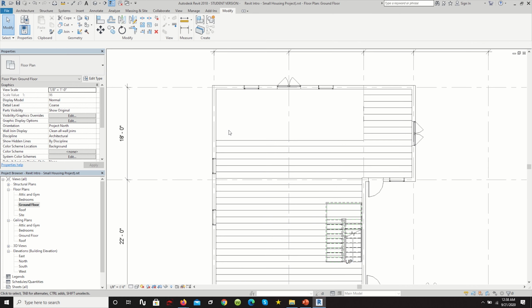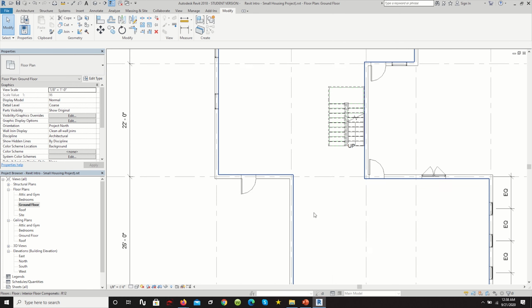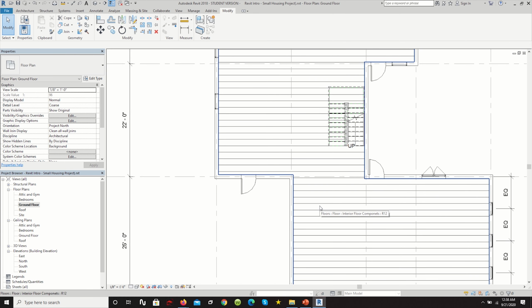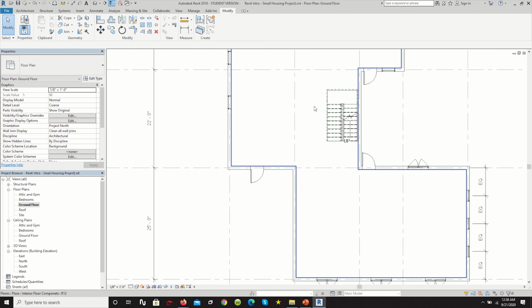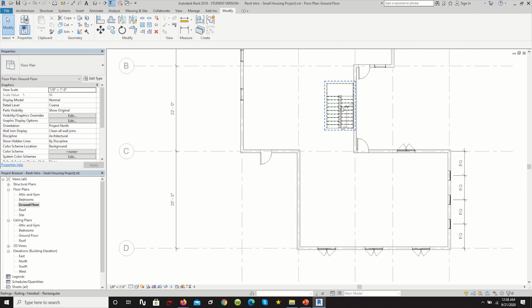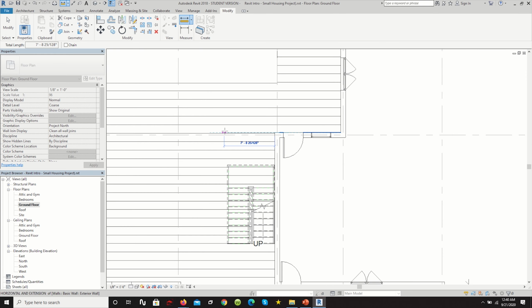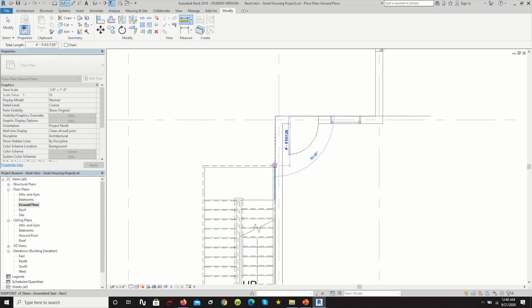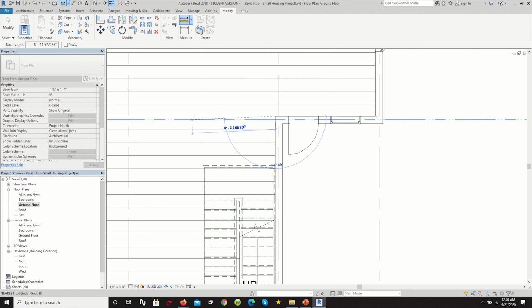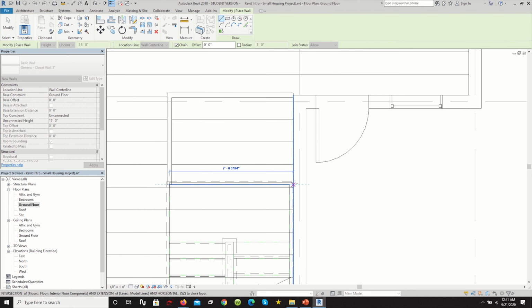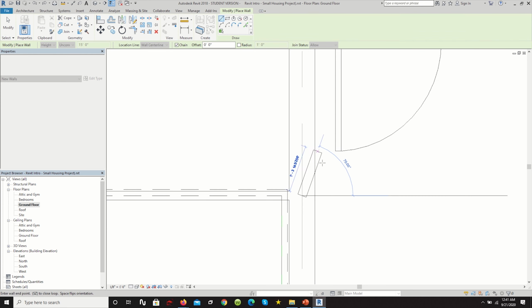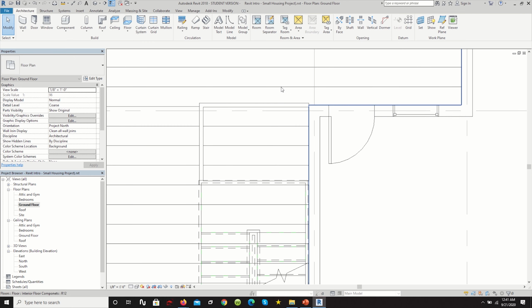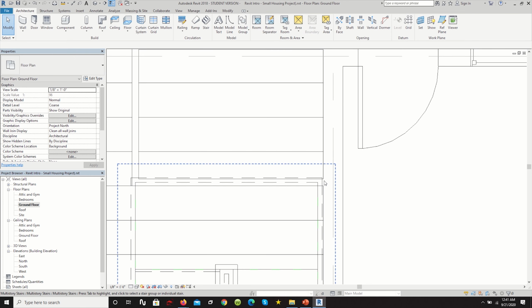And then here we're going to make a layout for the kitchen. First things first, I actually also want to specify a powder room on the first floor, that way you don't have to have guests coming up into your private area on the upper levels. So here would be a good location to add a powder room. Powder rooms are typically about 20 square feet. We can enclose the wall over here, lining it up with the edge of the staircase.